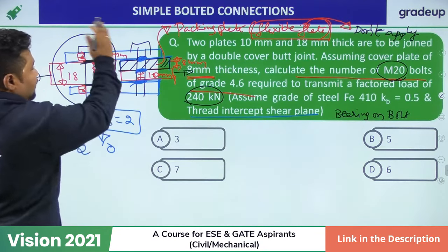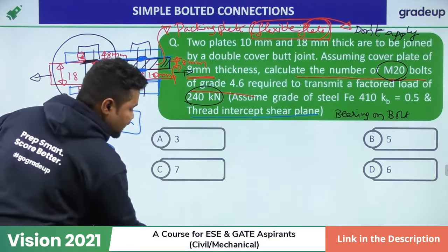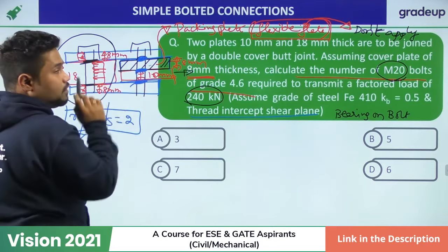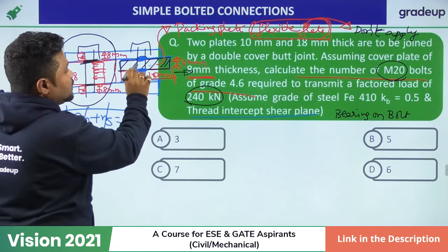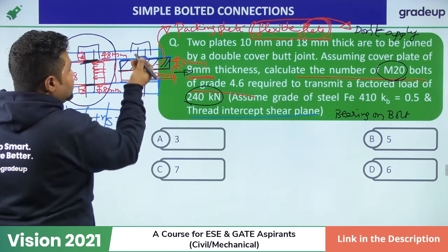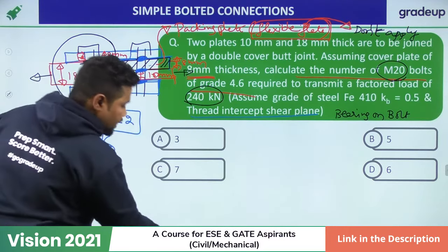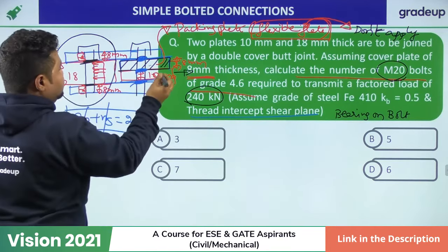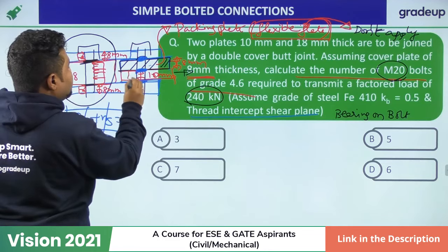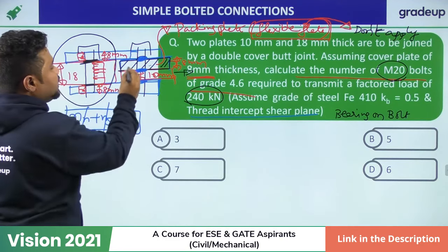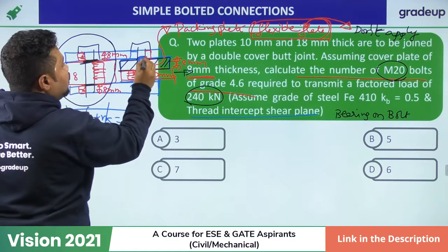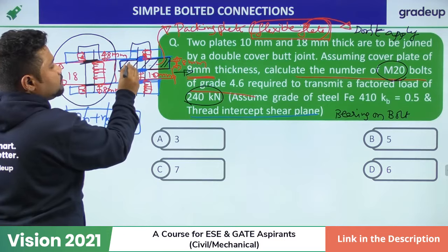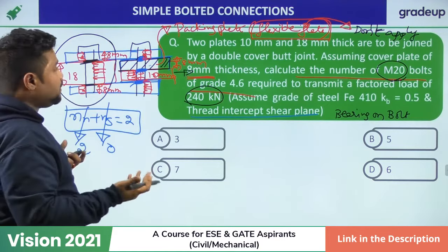But for this left hand side joint, if you take the right hand side joint, because this is a flexible element, it won't apply any sort of bearing pressure on this bolt. When this load is applied in this way, you can only see the bearing stress applied on this bolt and on this bolt. But over this, the packing plate is not applying any sort of bearing pressure.